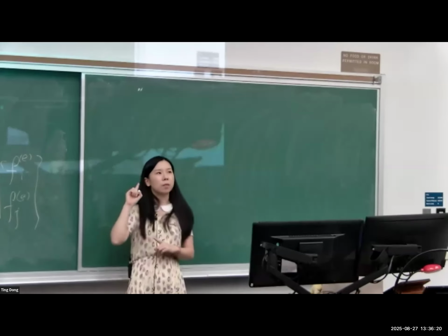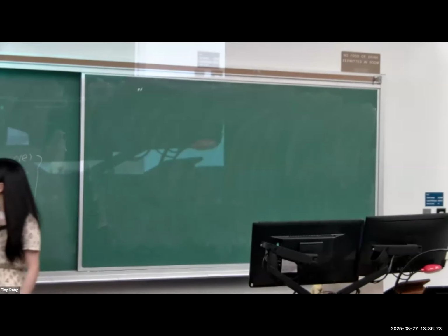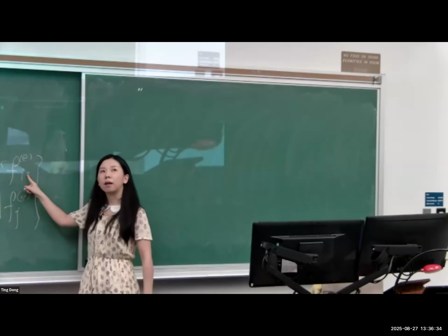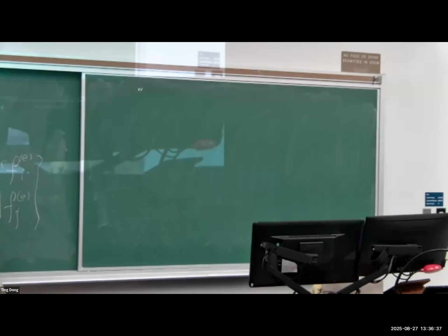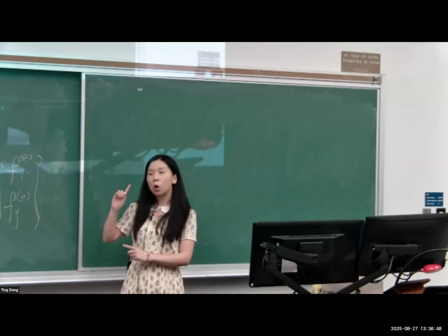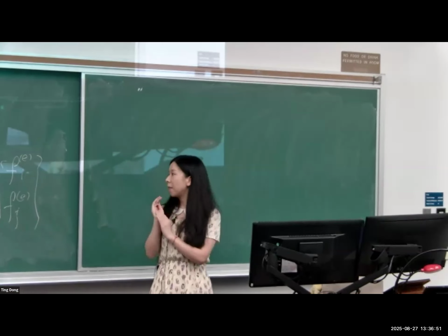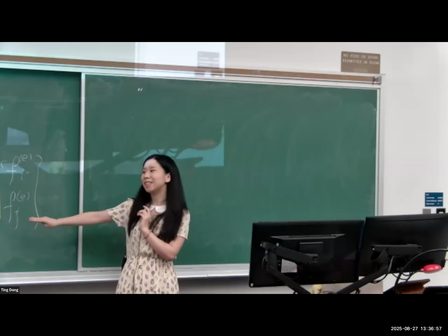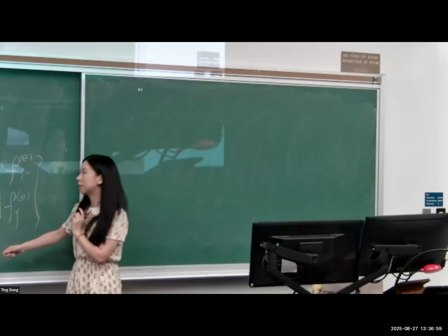So the two equations we put in matrix form is simply K. The first equation, you can check, is K times Ui minus K times Uj equal to force at node i, right? The second equation is K times negative Ui plus K Uj equal to Fj. So it should be the same, I just write a different form. And now this is the first matrix equation we learned in our FEA class. This is the matrix equation for the spring element.